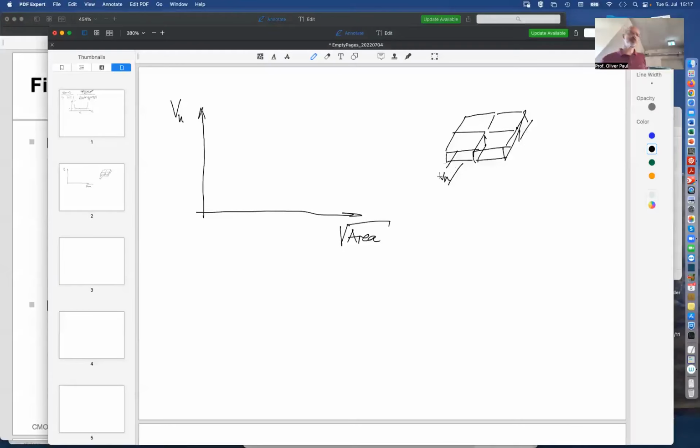what you will measure here is going to be the concurrent effect of the noises of the different elements. But if those elements produce statistically independent noise, like separate detectors, and you're just adding the signals of those, then those noise voltages will be added, but they will be randomly added because these are random signals.